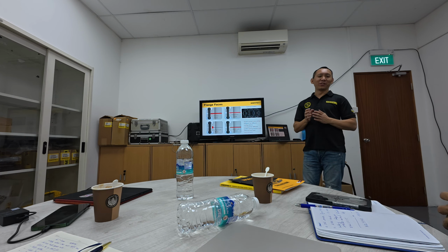So we need to know things like the thread pitch, what type of coating. The type of coating will also affect the bolt load. What type of lubricant we are using or tension. So things like coating, material grade, especially you need to know the material of the fastener. Coating also affects what kind of lubricant brand we select. The amount of lubricant that you apply will determine the model of the tool range you use.